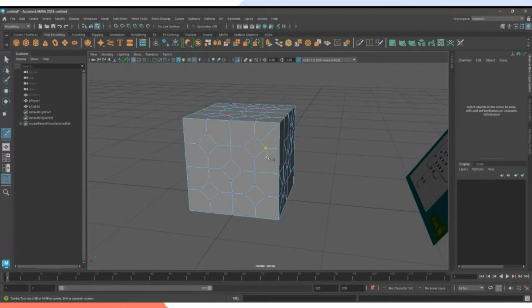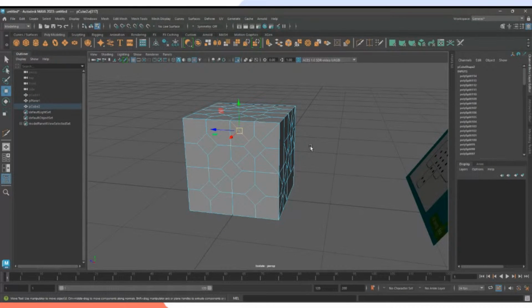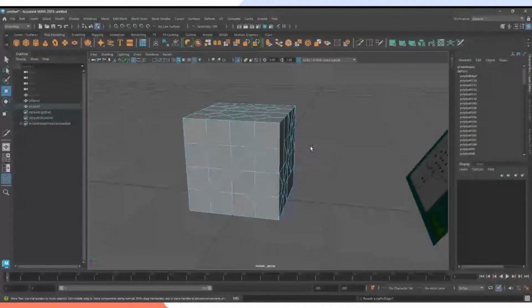Oh, by the way, if you have any mistakes in trying to select your position, for example, like that, but it's actually wrong, you can just press the backspace key if you want to undo any of those types of mistakes. Another one is when you go to edge selection, if you see something that you don't like, this is actually wrong, you can just press control backspace.